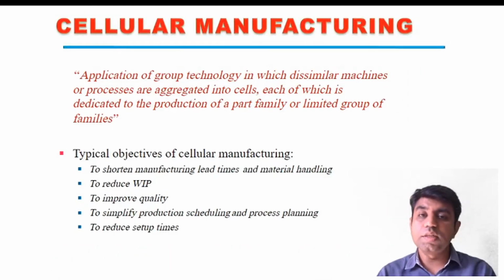Now let us understand the concept of cellular manufacturing. Cellular manufacturing, as we had already discussed, is where in group technology we are making different machine cells, right, as per the different part families, right? So in each and every cell we have dissimilar machines.